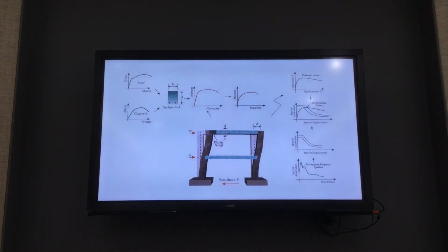So you take that as a starting point, and from that pattern you reverse calculate what forces will be required to produce a deformation consistent with a modal deformation. So then the question is, which mode? Mode 1, right. So this is second problem with this method, that it is only good for one mode.